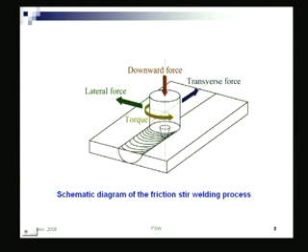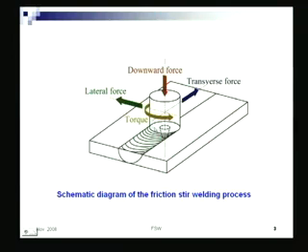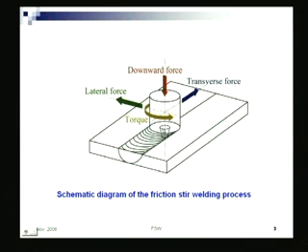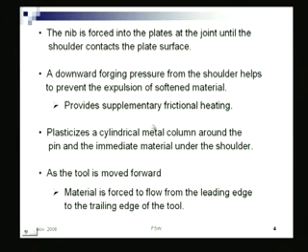So that is what it says, that this shoulder prevents that from happening, but you should provide a space for it. So what is done is this shoulder is made a little concave inside, such that it can accommodate that expelled material, and also that provides a supplementary frictional heating. That means primary heating is from the nib, and then additional heating from the shoulder surface.